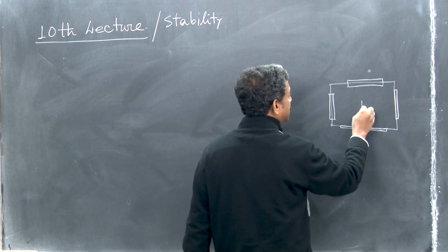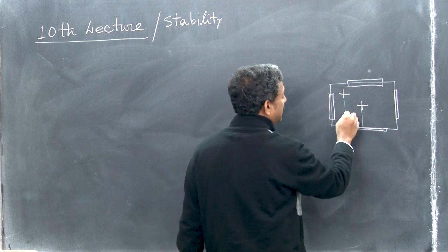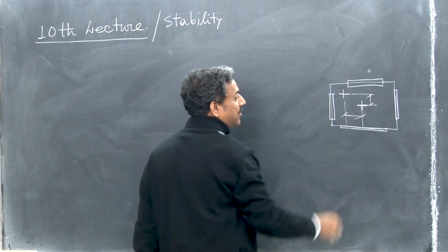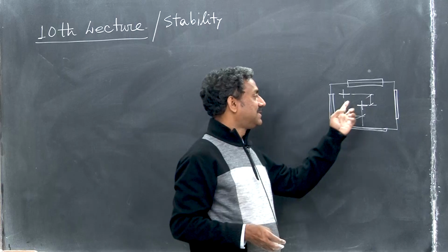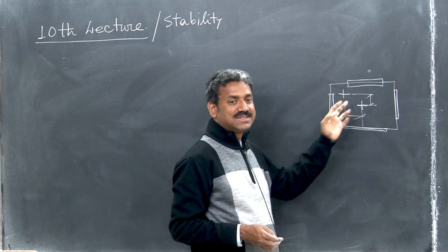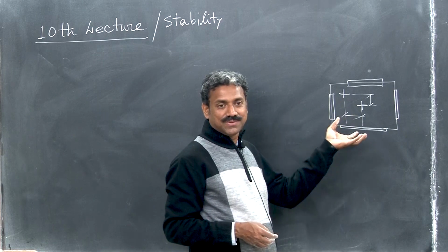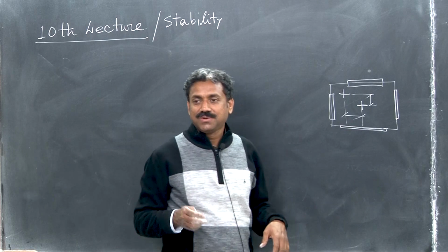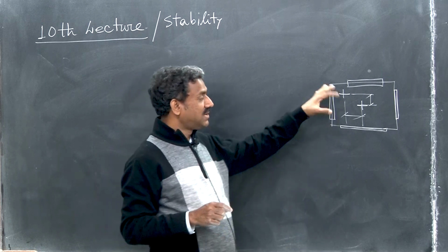Then whatever is the center of mass, your center of stiffness is towards the heavy walls. So you will have this eccentricity, right. This is the center of stiffness. The role played by the shear center here is similar to that of the CG; here is the CG and here is the center of stiffness or center of rigidity. Then this building becomes torsionally coupled, and of course you need to increase the demand by some percentage on the other side.